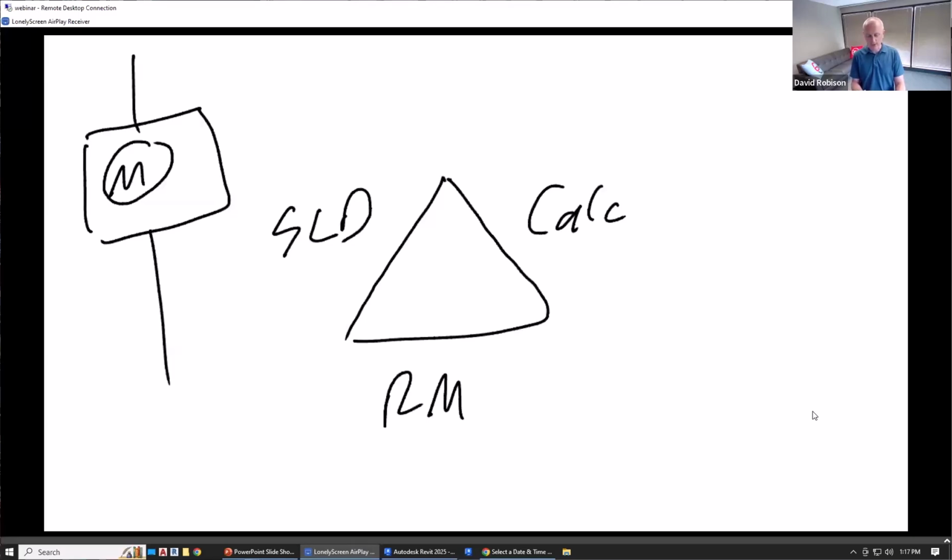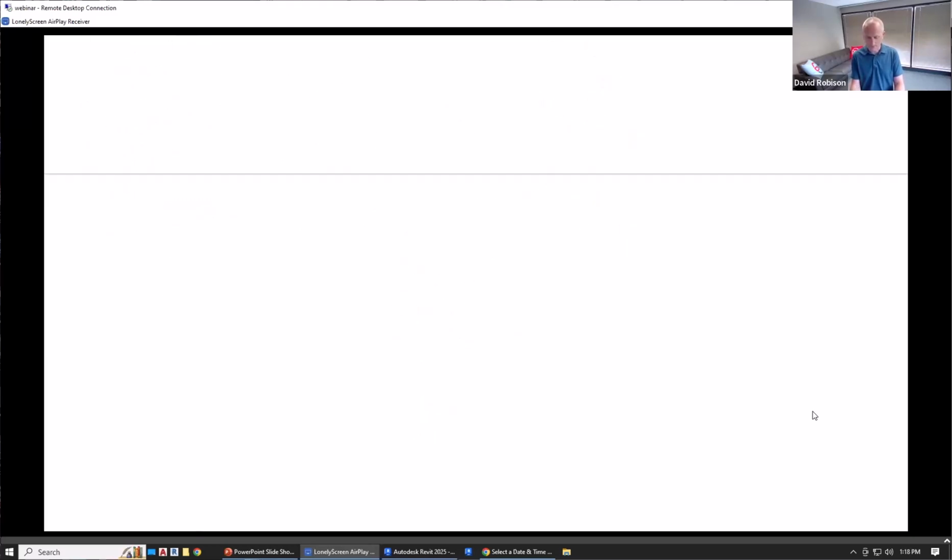So the electrical design triangle helps you think through where else you actually need to make this change. In this case, it actually doesn't impact the Revit model at all. The same with the calculations. The meter isn't really going to impact the voltage drop or your wire sizes, so it might not show up in the calculation. So something like a meter is straightforward. It's some drafting on the single line diagram. It doesn't impact the other two places.